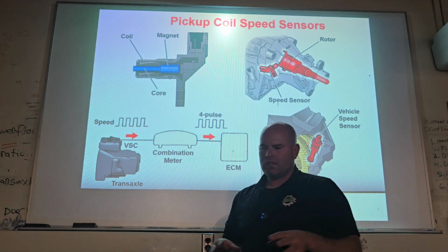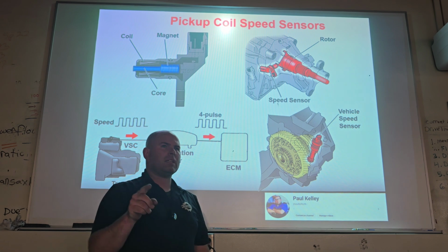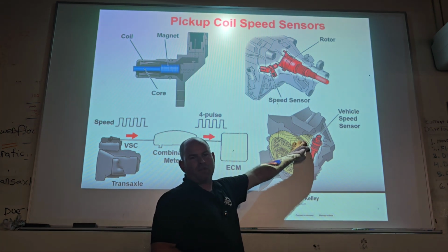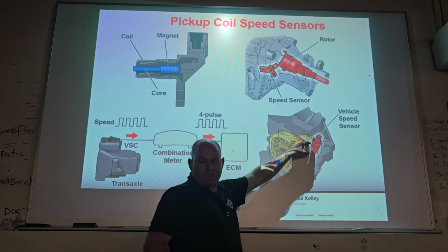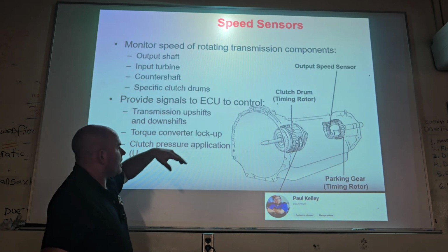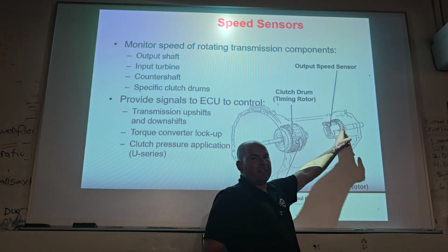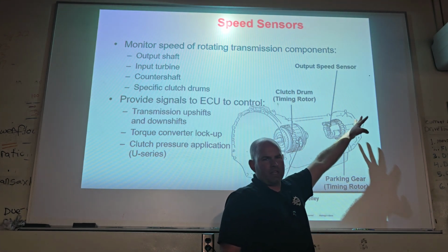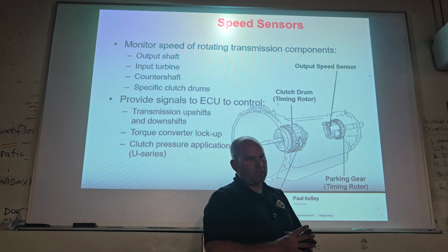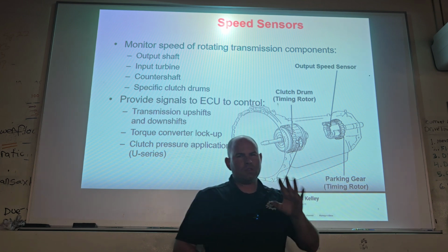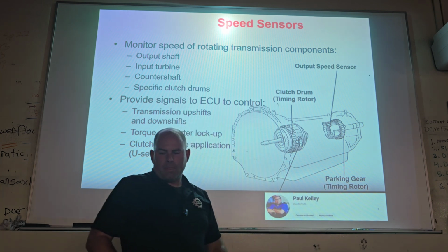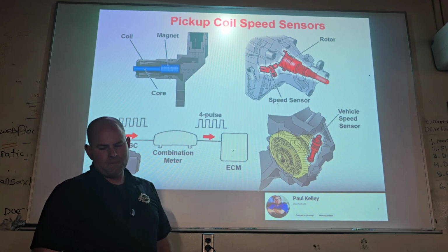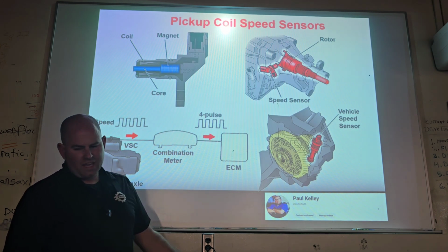Vehicle speed sensor tends to be on a transaxle because they measure it right off the diff, off the final drive. Whereas in a rear wheel drive, they tend to be more like an output shaft. This is not vehicle speed because it still has to go through the axle that's back there that's going to give it its final reduction. So mostly they're the same, but one of them is really output shaft and one of them is actually vehicle speed. Make sense?